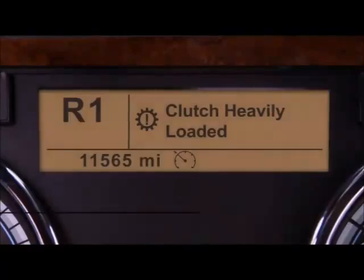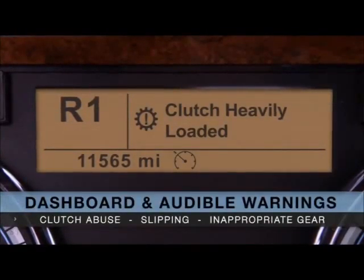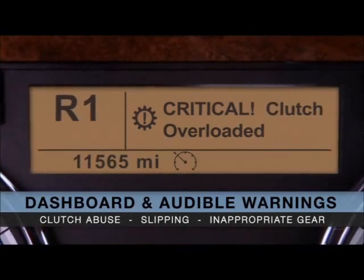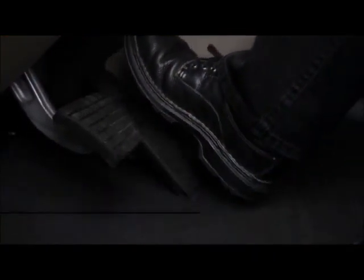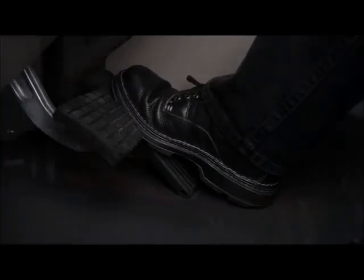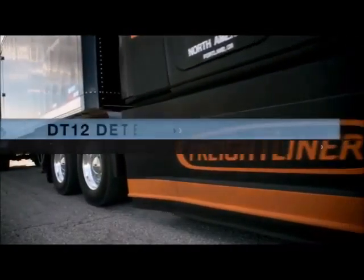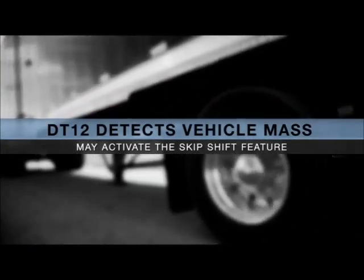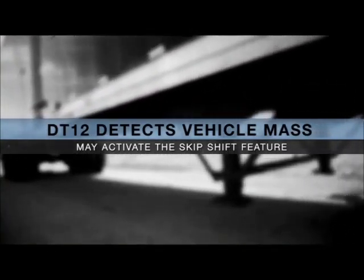Dashboard and audible warnings will alert you to clutch abuse, slipping, or starting in an inappropriate gear. The clutch will not engage until foot pedal movement is acknowledged by the engine. Once you're rolling, the transmission detects the vehicle mass and, depending on the road grade, may choose to use the skip shift feature.